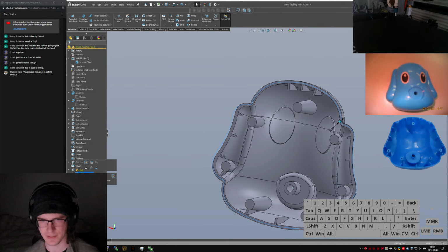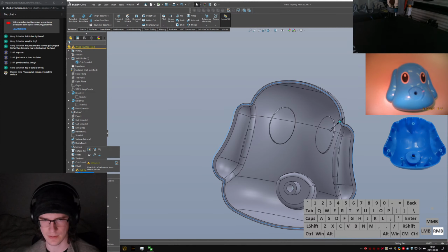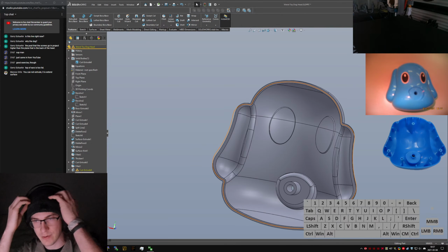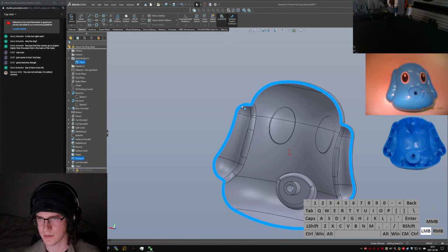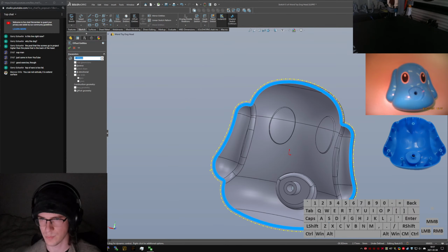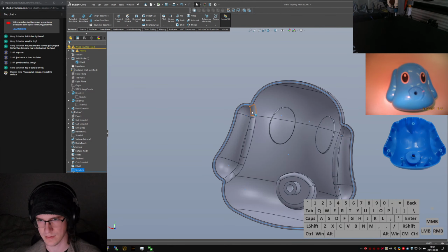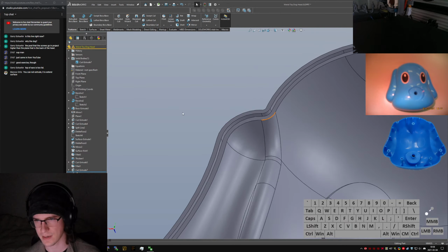And then we've got this. Actually, hang on. I don't like this cut. You know what? No matter what I do on this cut extrude, it's going to break a whole bunch of things. So I may as well delete this, do a sketch on this face, offset, 0.3, reverse. Okay. Got our edge back. It'll always track the outside. Extruded cut, 0.3. Got our lip back.